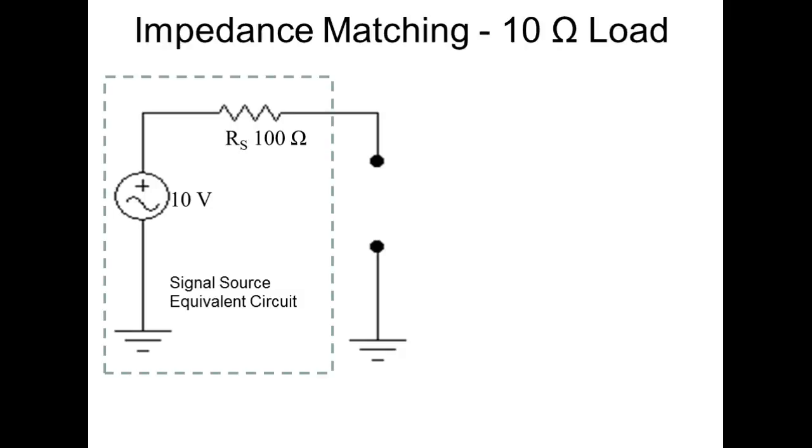They call it line loss. So even conductors give you line loss, right? And what determines the resistance of a conductor? What it's made of? The size, right? Or we call it the gauge, and the distance, and then the temperature. Power sources have resistance. So if you try to get current out of a power source, the voltage output will drop.